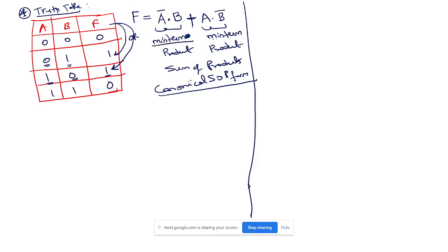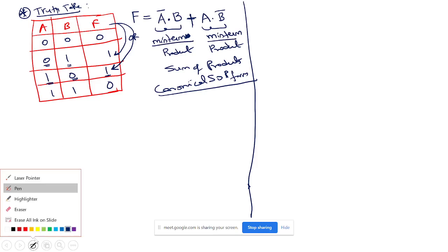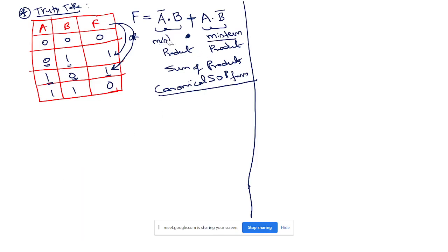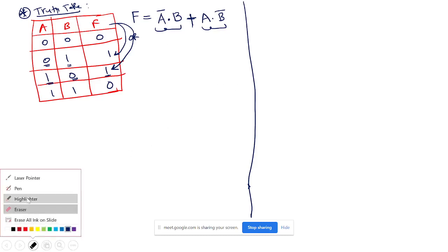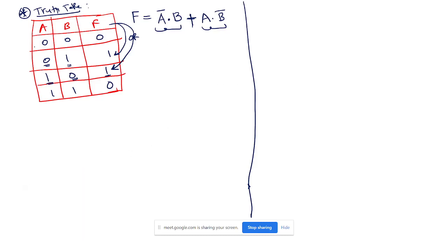Now, you see this min term is confusing, right? You need to give numbers because there are so many min terms that are possible. We took only two variables, that's why only four min terms are there. What if I take 100 variables? So many are there, so we should number them. How to number them? Very simple. This is a min term represented by small m. 0, 0 in binary. What is it in decimal? 0, right? I write min term 0.